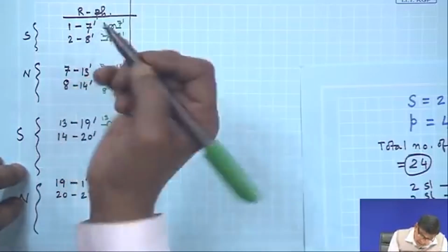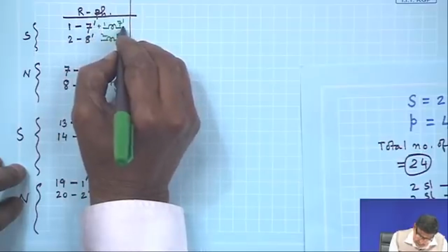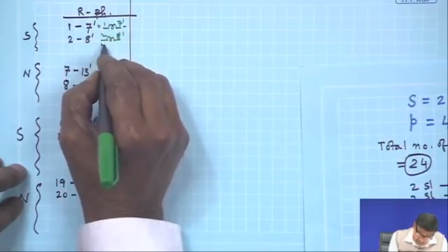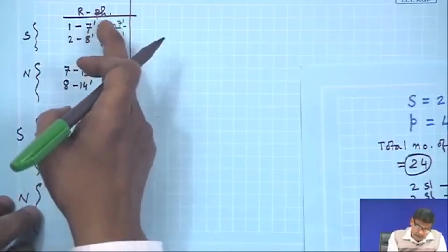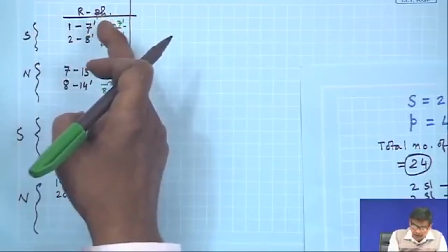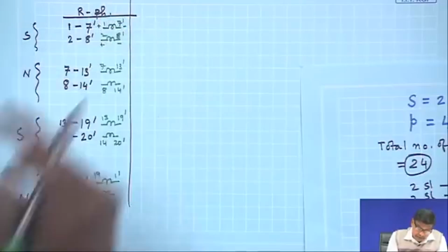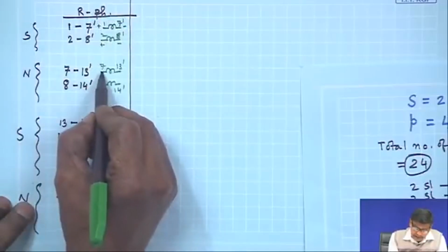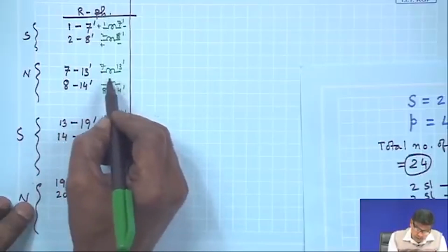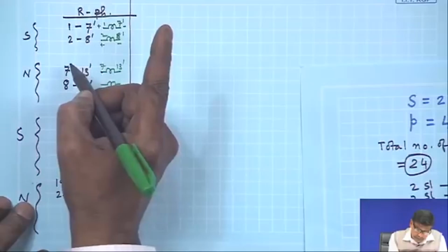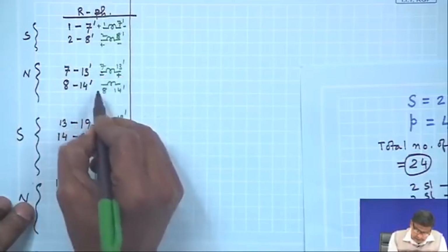Let us assume also that suppose this is plus, this is minus. So, this will be plus, this will be minus. But if you say that this conductor 1 under south pole, influence of south pole has a plus to start terminal, then this side is also the start of another group of R phase coil, but it is under north pole. So, it must have terminals like this.